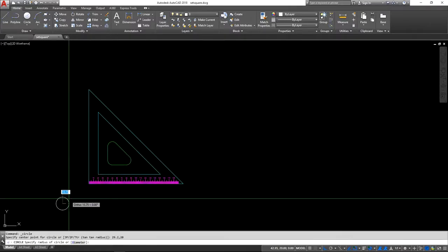Now there's a number of reasons that could be. The first thing we need to do is find out where 0 is, and that will let us determine whether it's gone to the right point or not. The other reason why it could have gone there is also because we were using dynamic inputs. Now dynamic inputs uses relative coordinates. So what that means is wherever your last 0 point was, it will now draw your coordinate based from that point. So the last point becomes 0. That's not quite what we want in this scenario.